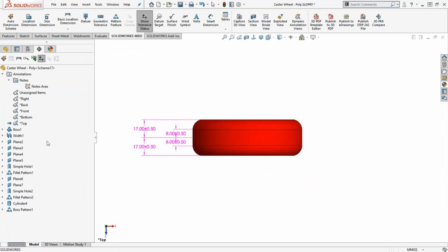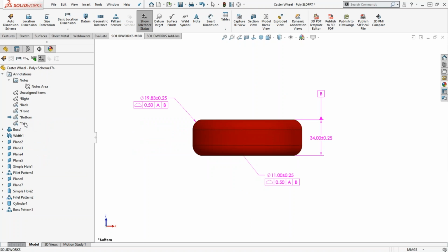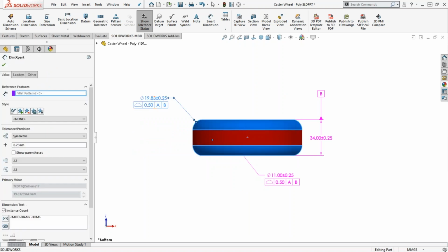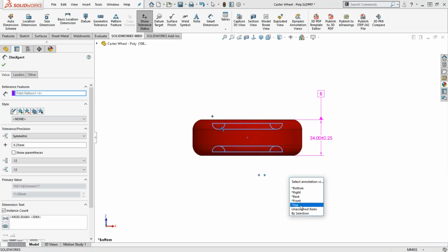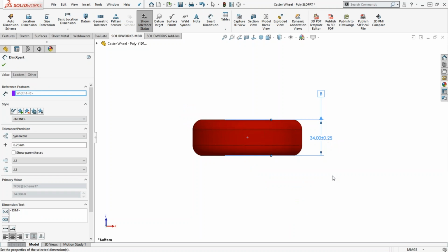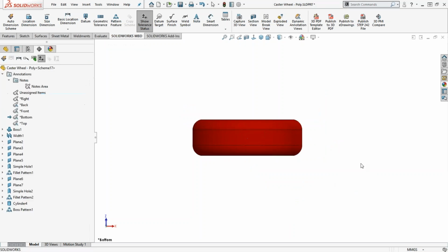Let's go ahead and activate and reorient to the top view. We've got those guys right there. Now again, since top and bottom view show essentially the same profiles, let's go ahead and move this bottom view information to the top view. So again, I'm going to select the annotation, click the tilde key, and choose top from the menu. I'm going to do that for all three of these. Top. And even my datum callout here. Top. All right.